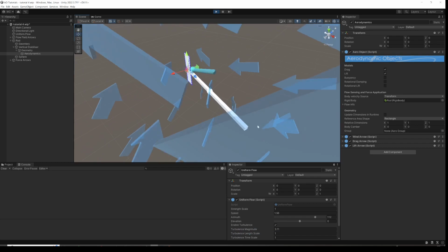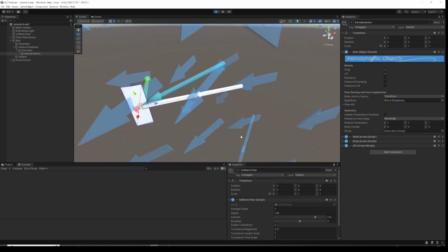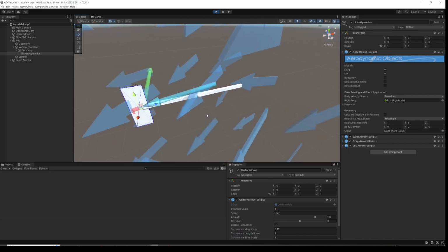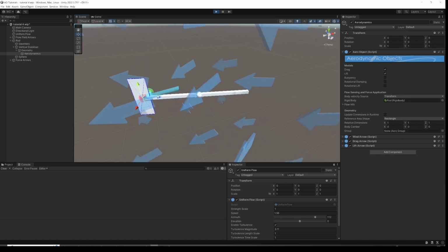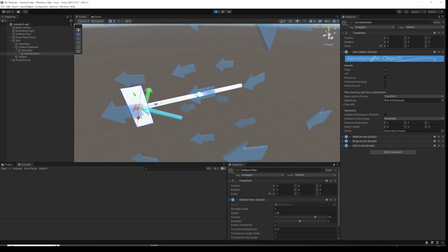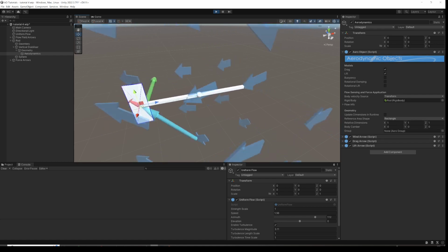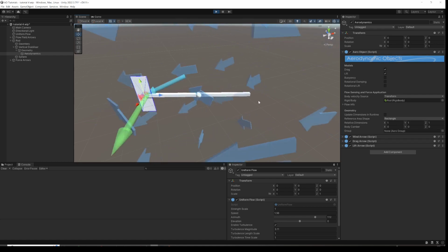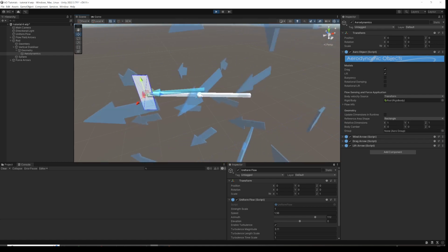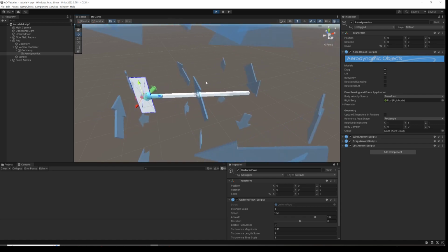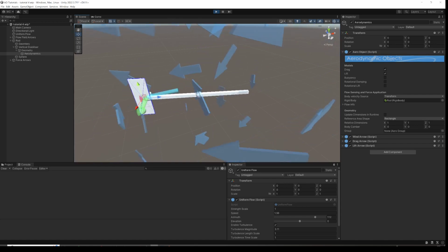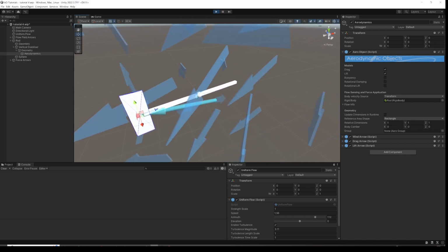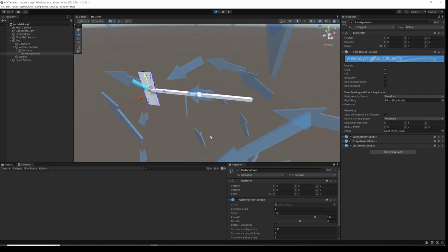And just while we're here, I talked about changing the velocity source for the aero objects. It's all moving rather quickly, but the blue arrow here is the velocity sensed at where the fin is, and the blue arrow here is the velocity sensed where the rigid body is. So actually under this setup with lots of turbulence, it's quite important that you change the reference point to where you're getting your velocities from to the transform.